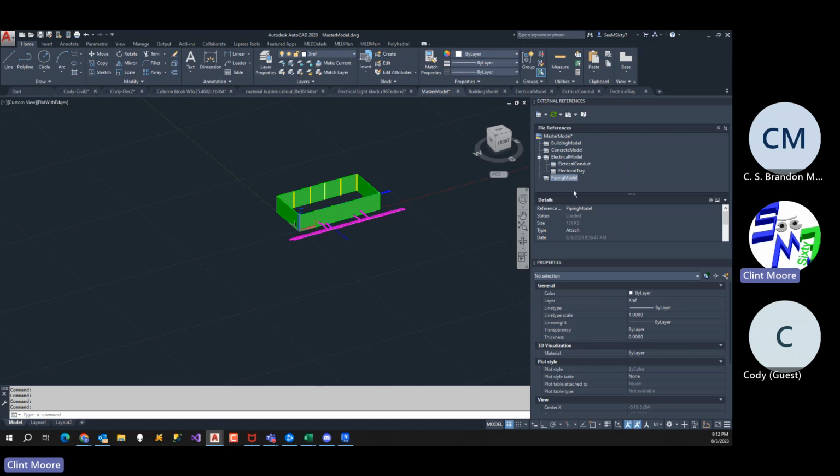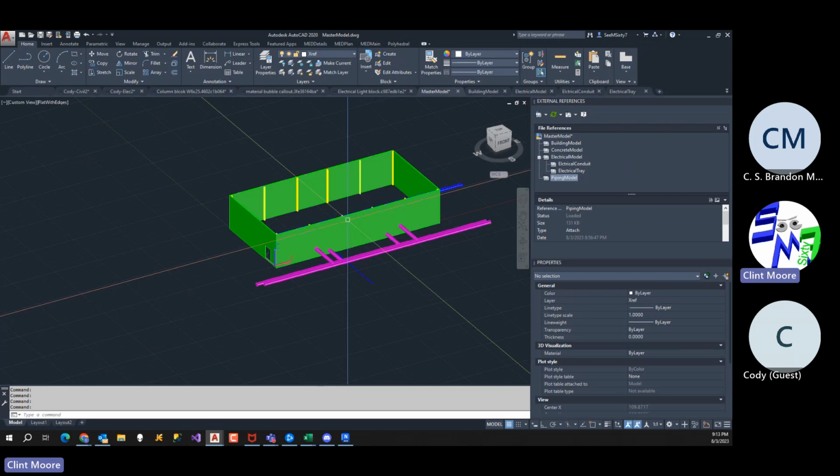And then that piping model would reference in all those individual piping sets, because if you have a group of pipers working, so you have one guy working on drains, one guy's working on fuel gas, one guy's working on instrument air, and one guy's working on main process piping, then you can have 4 different files and 4 different processes going in that effort. And so they could actually all be working and developing this model at the same time, instead of one person having to work on that one particular file. On a massive job, you might end up with that kind of thing. You might actually break it into areas and such like that. Similarly with the building, you could have steel, you could have columns, you could break this up into all kinds of different parts and pieces of this particular thing here as well.